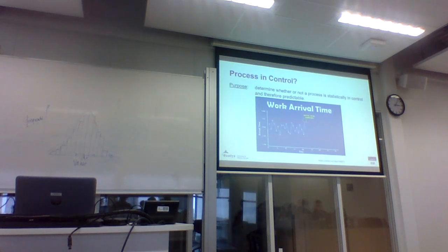So control charts help us separate and visualize common cause variation and special cause variation. And that's really what separates control charts from your basic run charts or time series plots. But how exactly do we determine what is common cause from special cause? In other words, where do we draw the line on what amount of variation is considered common? Because as we talked about, there's always going to be some amount of variation, but the key is determining how much variation is abnormal. So this is where things get into the statistics, but don't worry, I'll keep things somewhat light for now. Basically, some people that are much smarter than me have come up with ways of determining where we should draw the lines between common and special cause variation in the process.